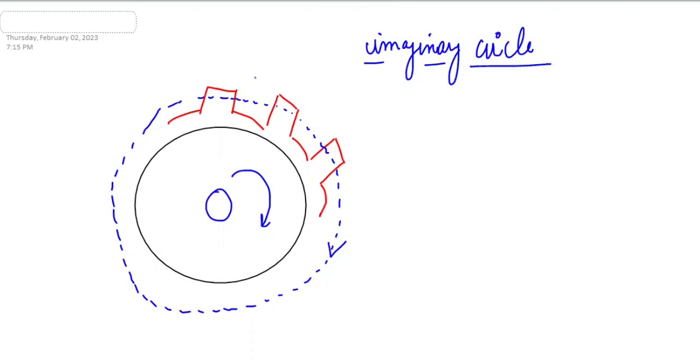In gears, the pure rolling motion is observed in the middle of the gear teeth. Why does this circle become important? Because if you want to see pure rolling, then whenever two gears are meeting, their pitch circles are in touch with each other. It is not a physical characteristic of the gear, but it is the most important circle, one of the biggest specifications of a gear.